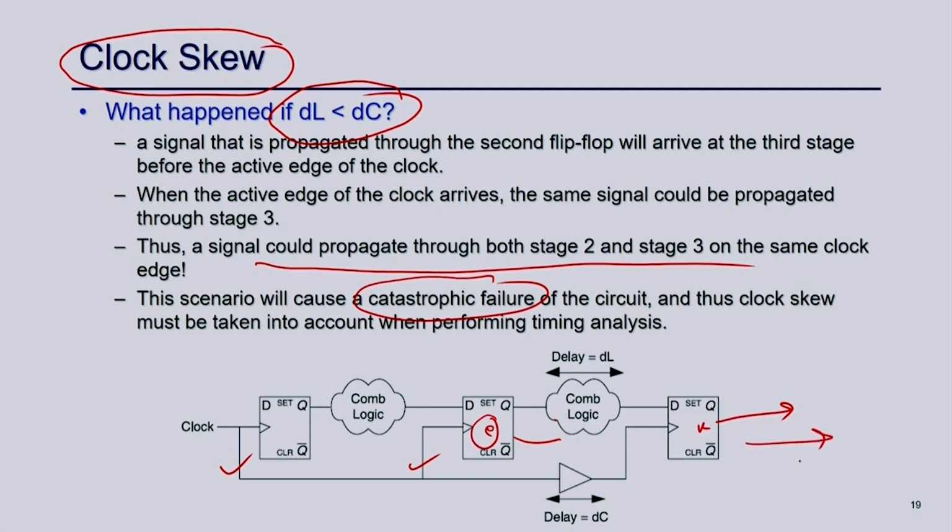So, that means whatever data is coming at the input, after 1 latency, 2 latency and 3 latency will go to the output, right. So the same data is not propagated further. If you have one data here, 1, that will not be propagated here as well as here, because that is not allowed. Whatever data is here will come in the next clock here, then it will come here, right.